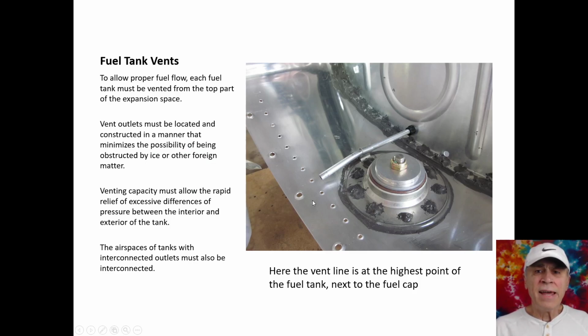Here's the fuel tank vent. This vent line is at the highest point of the fuel tank next to the fuel cap. To allow proper fuel flow, each fuel tank must be vented from the top part of the expansion space.